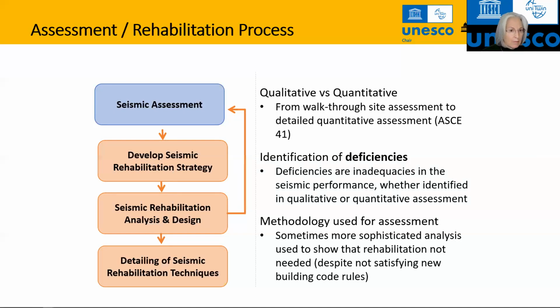So the seismic assessment can be qualitative versus quantitative. As I said earlier, the graph that I've just shown is a very qualitative approach. But we can also do very detailed analysis. So, for instance, the ASCE 41-17, as we will see in a moment, covers everything from something as simple as a walk-through site assessment to a detailed quantitative assessment.